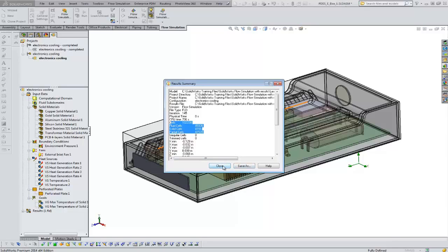But we want to understand if you've got an inordinately large number here, let's say you end up with something similar to this geometry and you've got 1.6 million, then probably want to back up, apply some mesh control, simplify the model, get rid of unnecessary detail, come back in, mesh it again, and try to bring that number down to a reasonable number. If we could bring it down from 1.5 million to like 700,000, that's going to be a much more approachable problem.